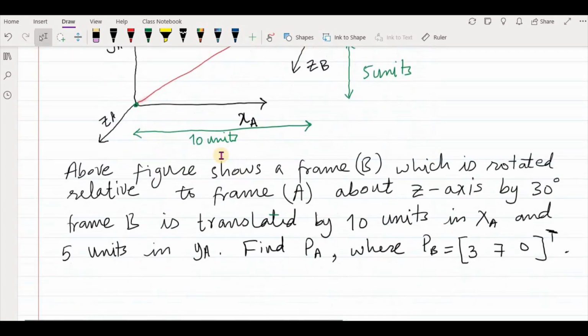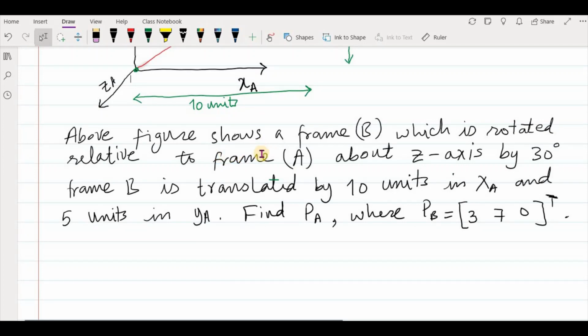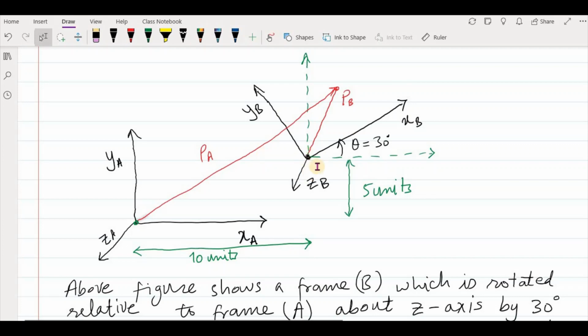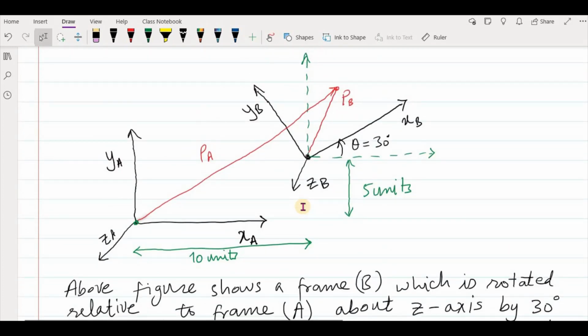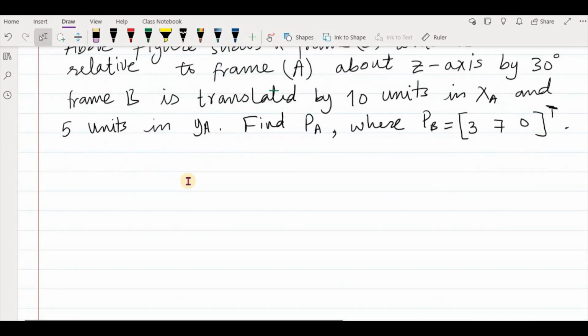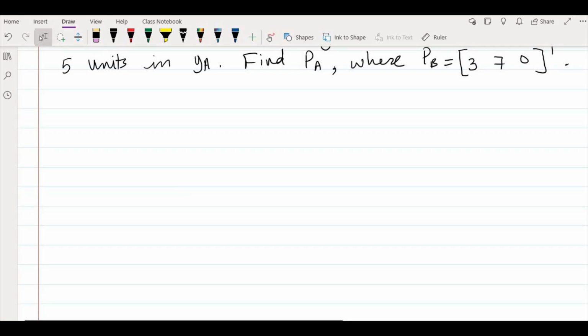In the previous lecture we did some of these kinds of calculations, but they were in 2 dimensions. This is also virtually in 2 dimensions, but we will consider the 3rd dimension too, and use it in the matrix. If you remember from the previous lecture, we developed methods like rotation and transformation matrices, which you can multiply for the transformation of one coordinate frame into another. Similarly we will do the same thing here, but this time we shall use a 3-dimensional homogeneous transformation matrix.